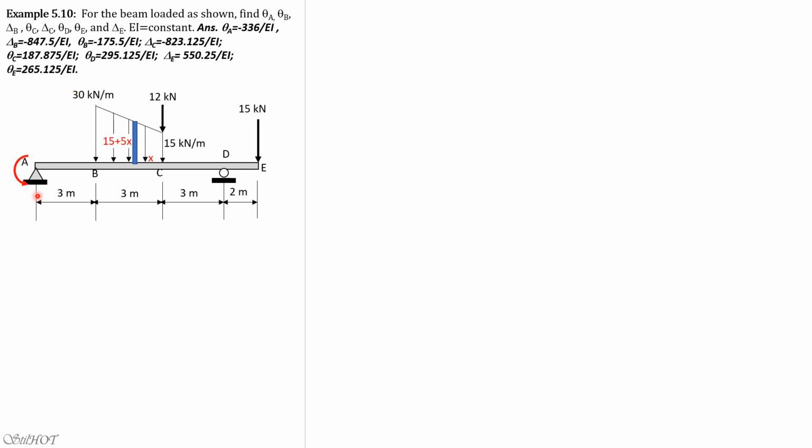This is the effect of the load at A, this is at D, FA. Then we have fixed moment at D, called FDL. So fixed moment AB can now be solved. Because we only consider AB, the moment due to the 15 kilonewton load at the overhang would be 15 times 2, so we have 30 there.